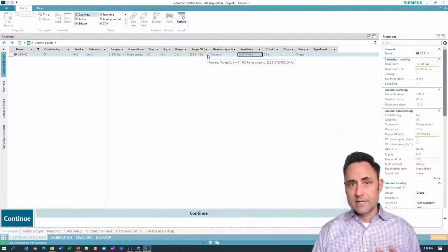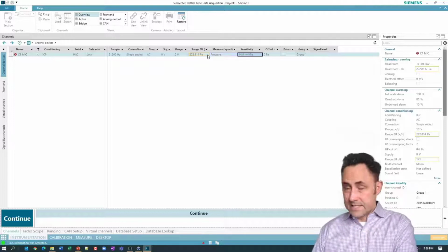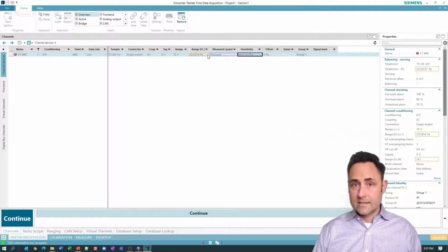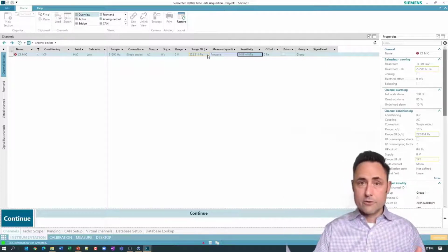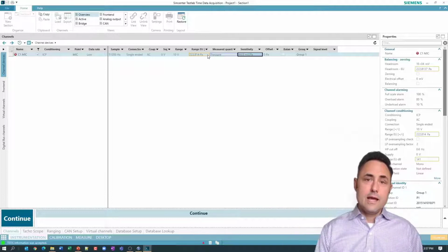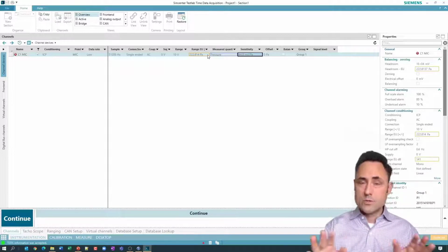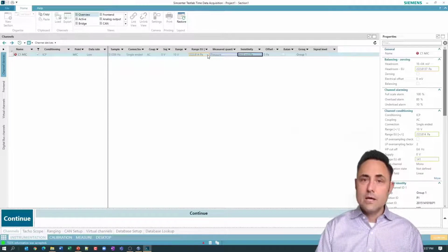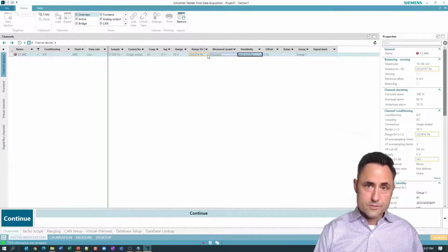Okay, so this is something I didn't necessarily talk about on the Scope app setting, but on the SCADAS XS and on most of the SCADAS mobile cards, you have an adaptable range. Wide open, or the biggest range, is 10 volts, and that's where I would suggest we leave it for this super high flexibility test setup, because we don't want to have it set at 1 volt range and then end up overloading. Once we overload, our measurement is garbage, and so we never want to have an overload situation. So I'm going to leave the voltage range out as big as it can be, which is 10 volts.